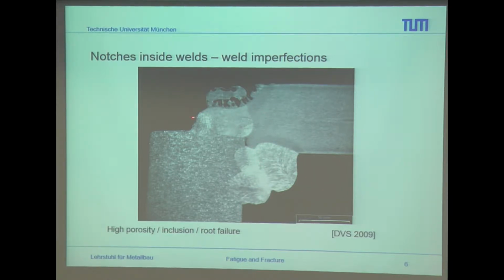On this side, the weld seam is going over the blade, so a crack can appear due to the overlapping of the weld seam, and in the end this weld seam cannot handle many loads or cycles.